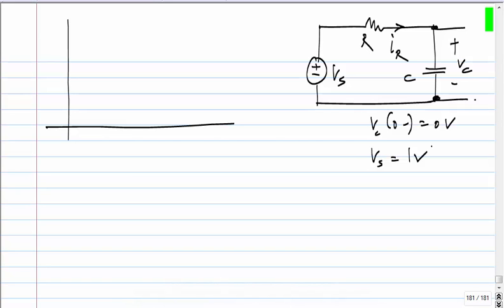Yeah, again look at the circuit and tell me what happens to the current. Obviously, if you have the expression for the capacitor voltage, you can find the current, I know, by Kirchhoff's law or simply by the capacitor characteristic. But now look at the circuit and tell me what is happening. What is the resistor current immediately after? Vs by R, or 1 volt by R. And after that, it will decrease. Yeah, it will go on decreasing because the voltage across the resistor goes on decreasing.